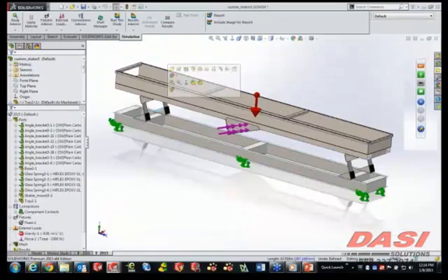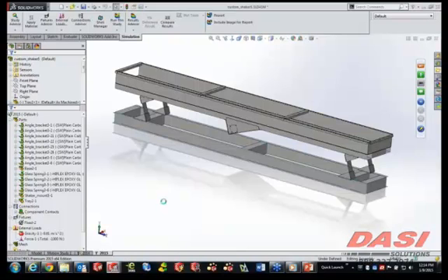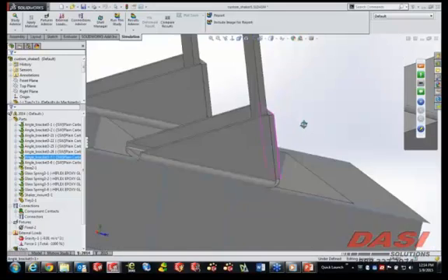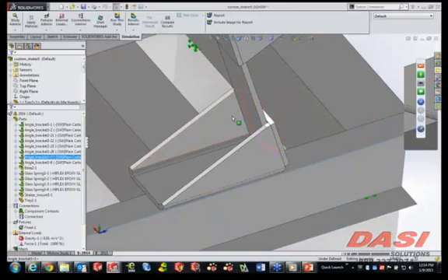Something that used to happen back in 2014 has also been addressed in a very nice way here in 2015. Here's a 2014 simulation of this particular file. On thin-walled geometry like these sheet metal parts, these parts would be simulated without any type of bonded contacts to themselves. We've always had contacts from one part to another, but not amongst itself.